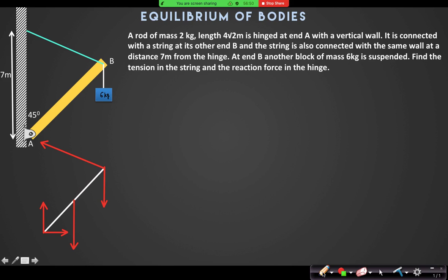Okay, I understand. You won't get the distance. All right, let's go. So this is tension T, this is 20 newton, this is 60 newton, this is horizontal force H, this is vertical force V. All these are the only forces acting on the rod, yes or no? Yes, sir. Now, about which point will I take torque? Obviously A. You have to take A.